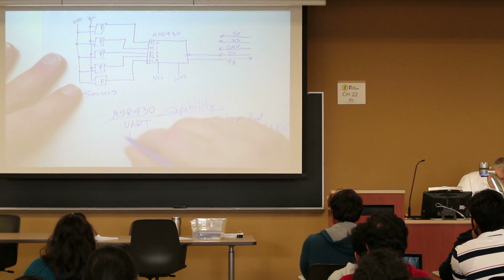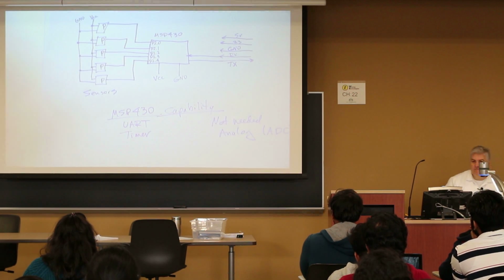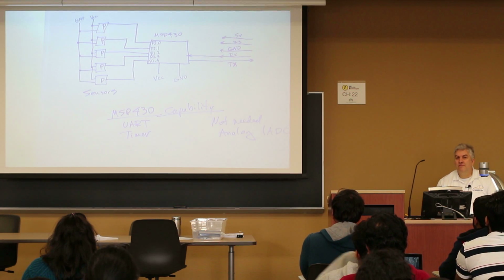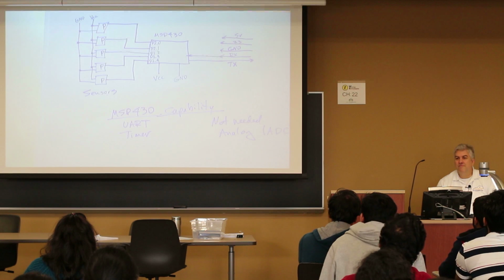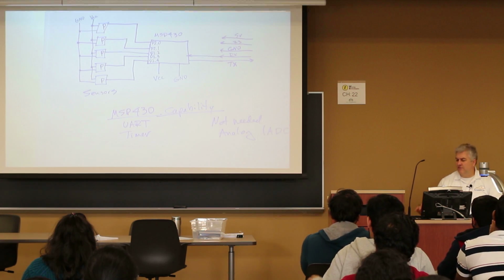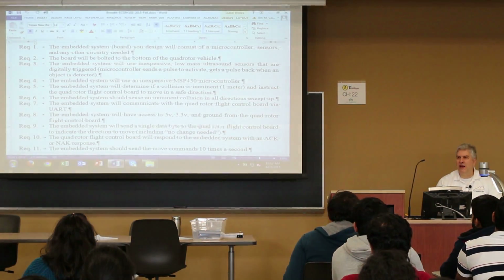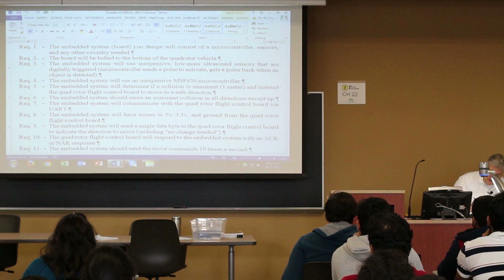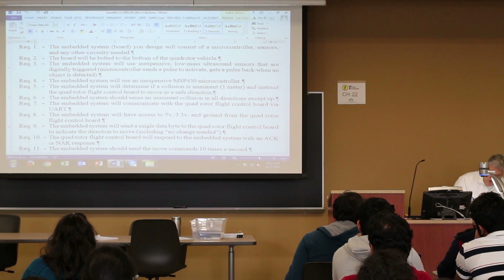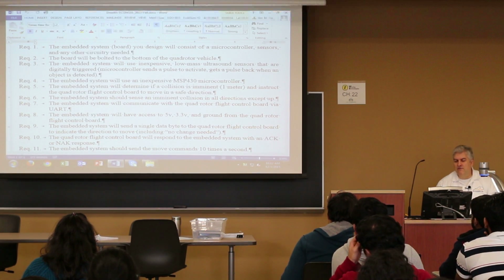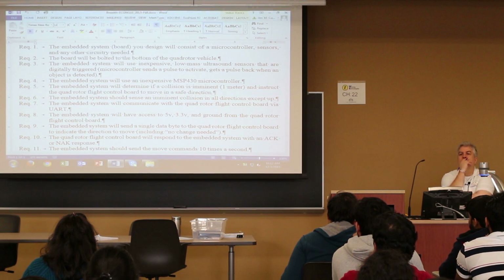Timer. How many? One. Just one? All right, how often are we sending information? 10 per second. So obviously you need a timer that's going to run how much time? 100 milliseconds. All right, so we definitely need a 0.1 second timer. Can you think of any other timer that you might need?